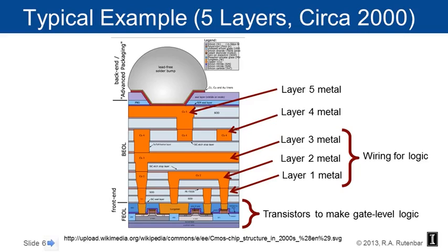And if you look very carefully at this, one of the things you'll see is that the metal layers at the top are a little wider and they're a little thicker. And there's a reason for that. This is a designed part of all modern ASIC kinds of technologies. They're designed to be a little wider and a little thicker so they offer less electrical resistance.